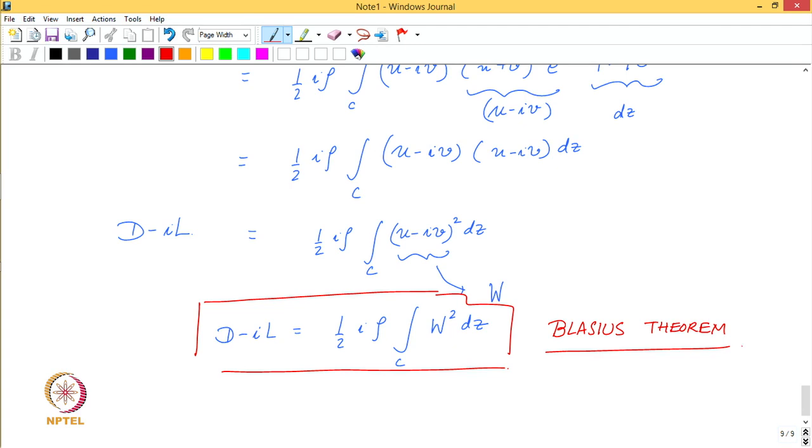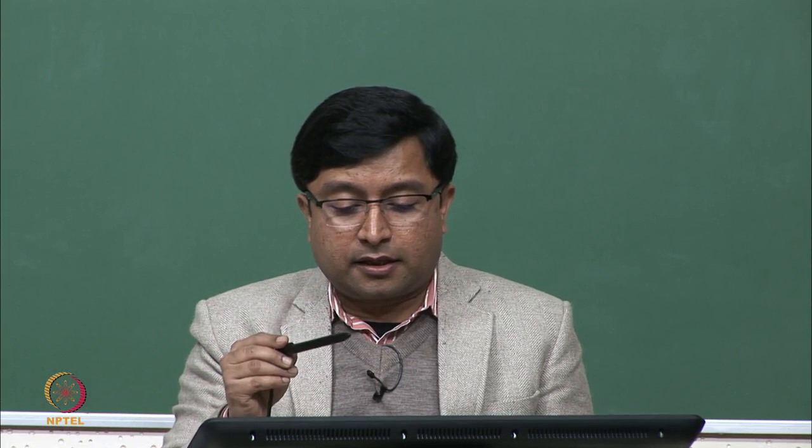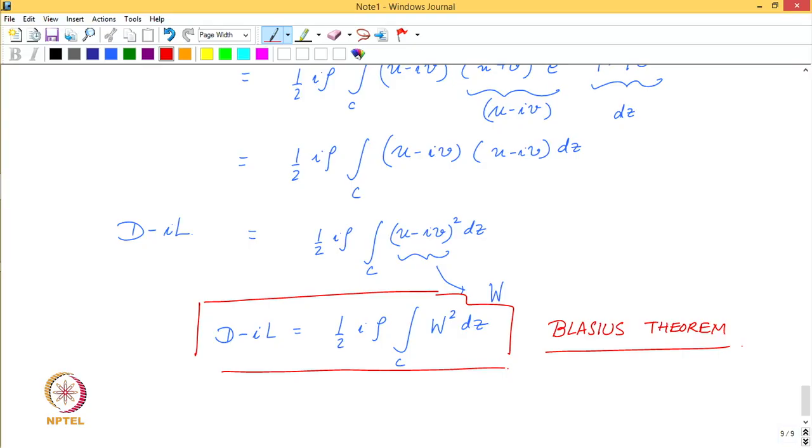Right. Now that we have done all this complex analysis, for any flow, if I know the velocity W on the surface of the solid, I could theoretically calculate this integral and derive the drag and the lift forces experienced by that solid quite easily, and that is the beauty of this whole description and this whole method. Okay.